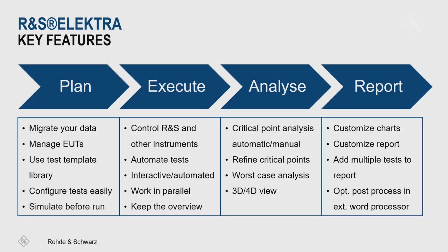Once you've done the test, we step to the analysis phase, where you identify critical points in an EMI scenario, for example, or where you do a worst case analysis on several test runs, or simply a 3D view on a measurement of a transmitting device.